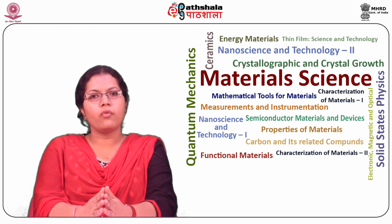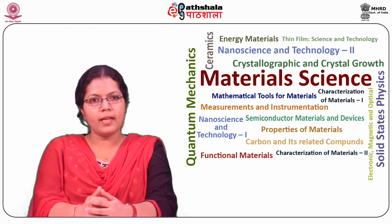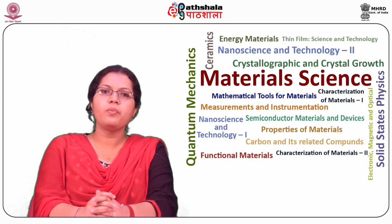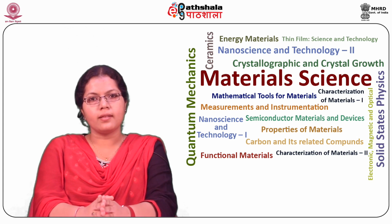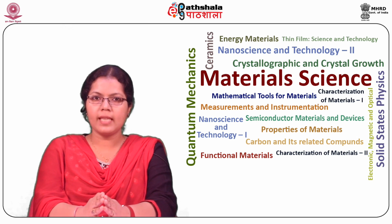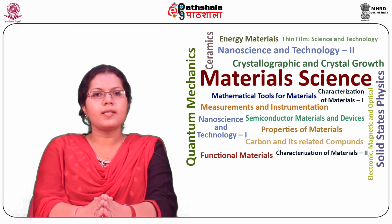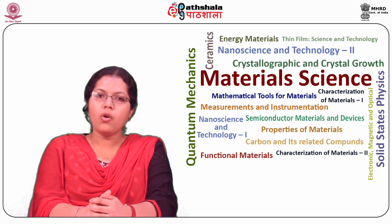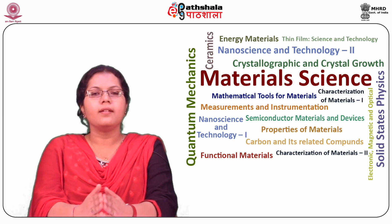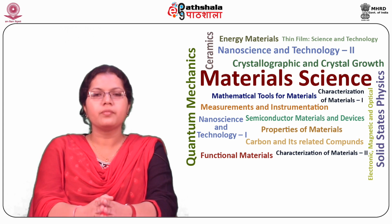Therefore, values of primary standards of capacitance can be known by measuring lengths. We saw that three types of constructions have been used for primary standards of capacitors. First, two concentric spheres. Second, two concentric cylinders. Third, two parallel plates with guard rings. Out of these, parallel plate construction is normally not used and the concentric cylinder construction has been discussed in the module. Thank you.